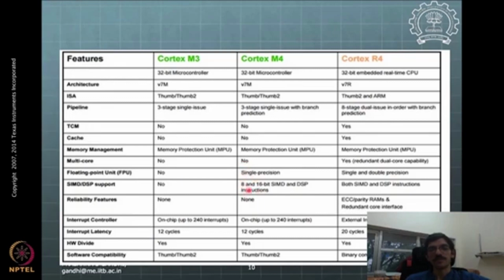Fundamentally, even if you don't know the specific data sheet of the microcontroller, as long as you know that it belongs to this Cortex M4 series, it's fine. You know that it cannot do double precision as a built-in feature in the microcontroller. One has to write a separate program. That means one has to expend more clock cycles to execute double precision on a single precision inherent microcontroller platform. So those are things one can see from a mechatronics perspective.